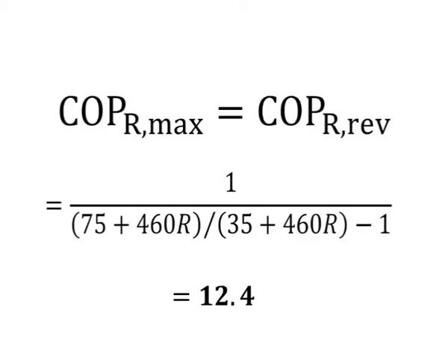This is the highest coefficient of performance a refrigerator can have when absorbing heat from a cool medium at 35°F and rejecting it to a warmer medium at 75°F. Since the coefficient of performance claimed by the inventor is above the maximum value, the claim is false.